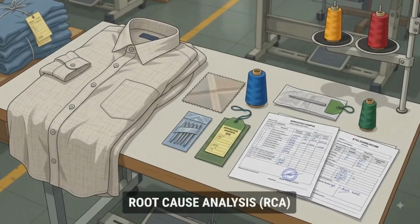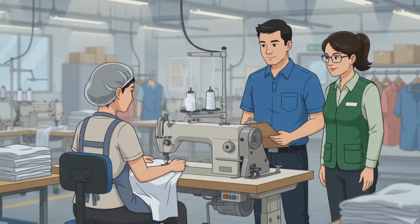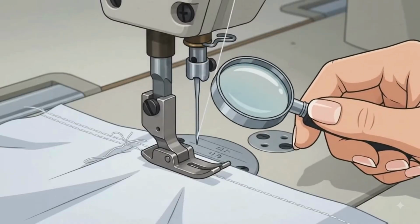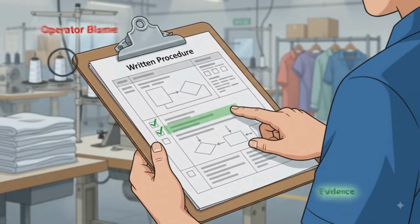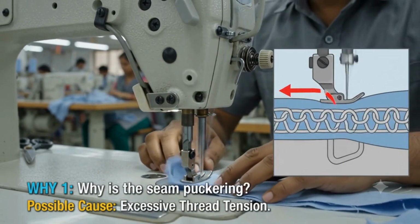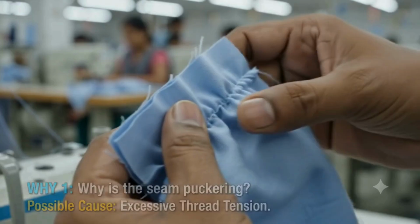Root cause analysis identifies why the problem keeps occurring. RCA examines evidence rather than immediately blaming the operator or accepting the first explanation. Why is the seam puckering? Inspection suggests excessive thread tension is drawing the fabric along the stitch line.